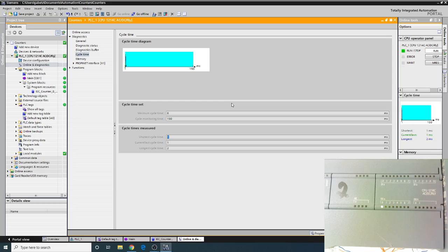All right. If I just have a sensor, right? I got a bottling line, right? And we're just swirling bottles past this thing. And I have a sensor counting every bottle that goes through. All right. If I'm looping at 1 millisecond loops, what's the max number of bottles this counter could count per second? All right. 1,000. Nope.